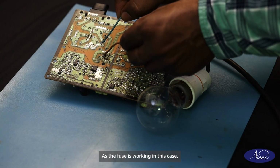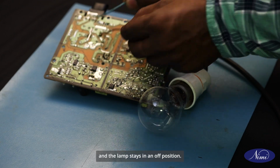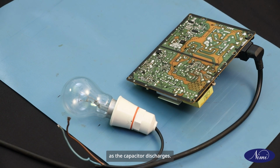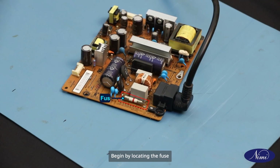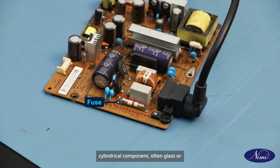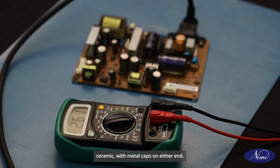As the fuse is working in this case, the capacitor won't charge and the lamp stays in an off position. But if the fuse is not blown, the capacitor charges up and then the lamp lights up as the capacitor discharges. Next, we will inspect the fuse. Begin by locating the fuse on the power supply board. It is typically a small cylindrical component, often glass or ceramic, with metal caps on either end.